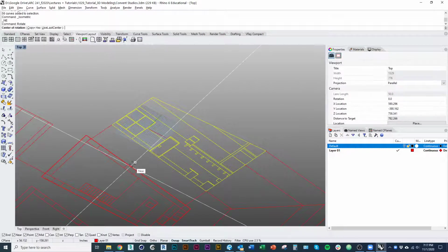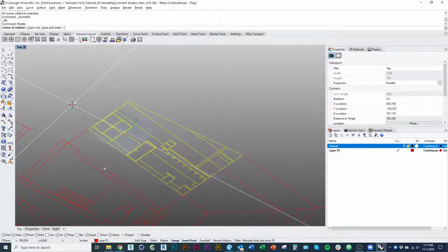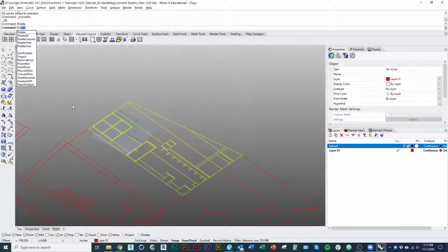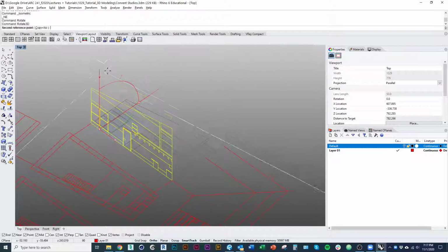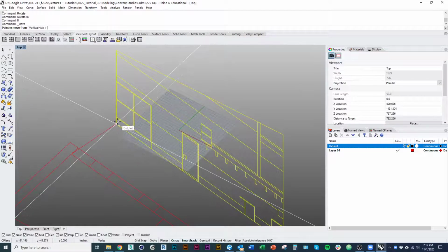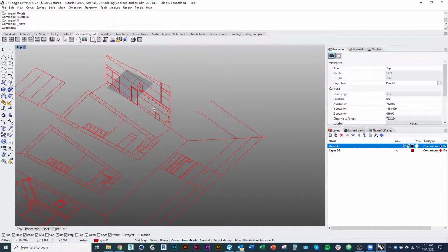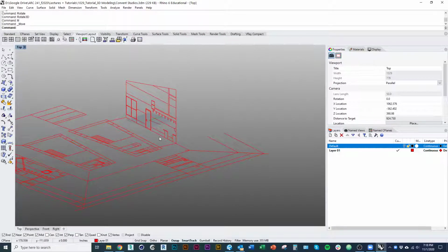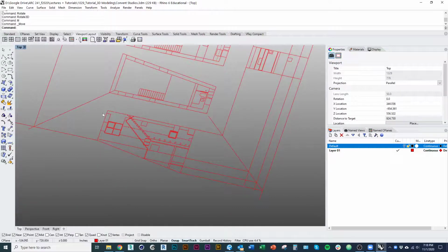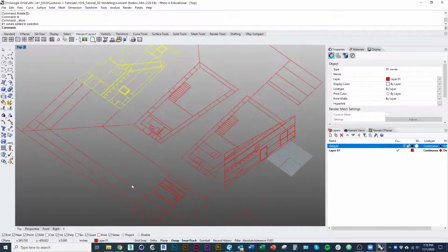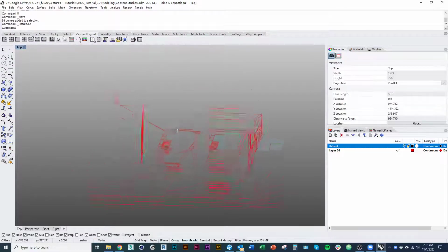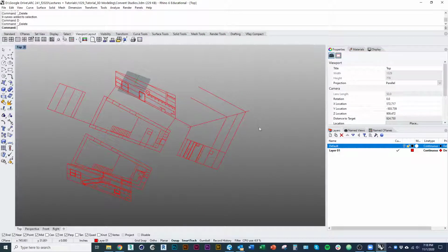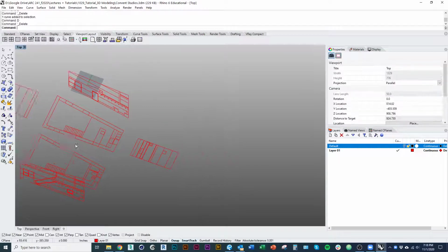So I'm going to start by orienting these drawings in 3D using rotate 3D. They're similar operations to what you developed first in project 3. At the moment, I'm just going to leave them off to the side, because what I really need these drawings for is to give myself an indication of what height things are going to be at. And I'm also going to do this big elevation on the other end here, which, as you can see, is oriented off in that direction, to use as a reference point. I'm just going to delete my construction lines now. I can always draw them again if I do need them.